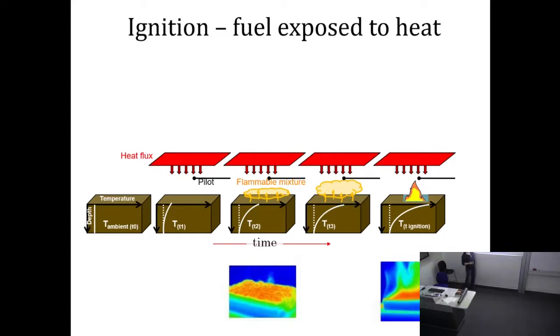But if it's exposed to heat, this being the ignition source or a nearby fire, then the temperature has to increase on the surface, and there is a point where the surface is so hot it actually starts to chemically degrade. The process of pyrolysis, which we have already seen, where there is a simultaneous change of chemical composition and physical phase. So the solid is a particular composition of a polymer, a hydrocarbon, in the solid phase, with long chains typically, and it's solid.